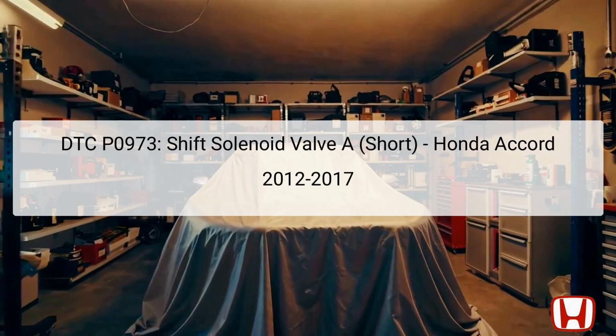DTC P0973 refers to a fault detected in the shift solenoid valve A of the Honda Accord models from 2012. This diagnostic trouble code indicates that there is a short circuit present within the solenoid valve's electrical circuit. The role of the shift solenoid valve A is to control the flow of transmission fluid, which directly affects the shifting of gears in the automatic transmission.